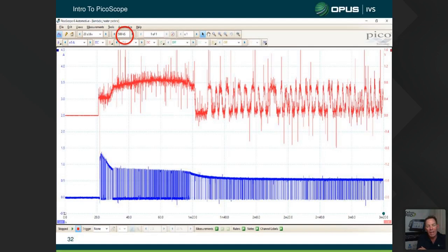If I'm measuring CAN bus, on the other hand, or FlexRay, or most systems, then I do want that as high as I possibly can. We want as many little dots in that little grid as we possibly can. Now, I say dots, but PicoScope displays it as a continuous line. But it's the way it samples. It's the way it actually pinpoints that on the grid.